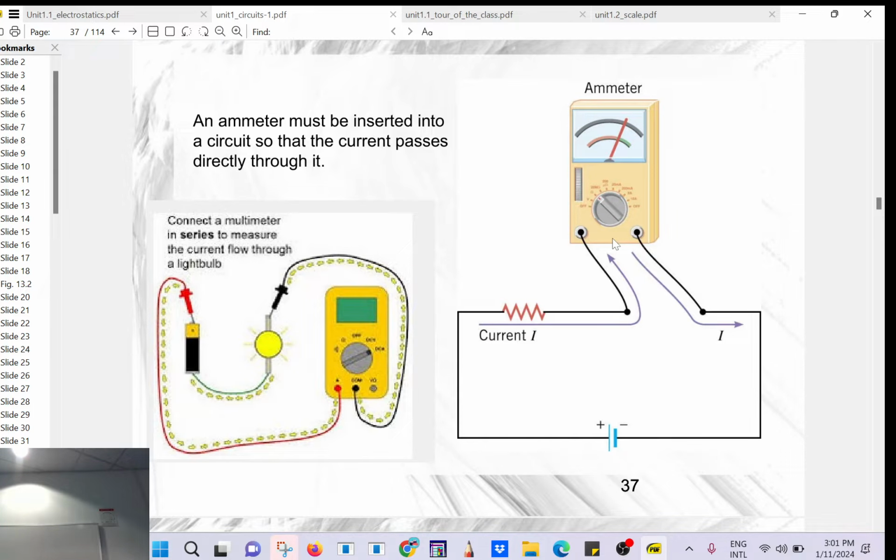I'm trying to measure current, right? I make a closed circuit. My load is happy, it's consuming energy. But here I'm not reading anything. And it says milliamps, but look here, what does it say next to it? 10 amps. So what do you think is happening here? The current is too much. Okay, so it's not in milliamps. I have to go in amps. So I'm gonna move that probe here. You see how it works?